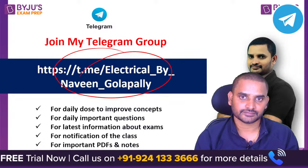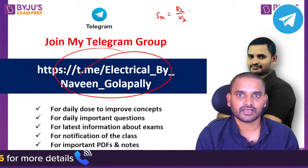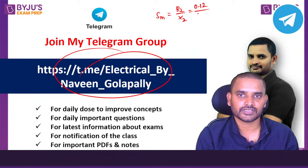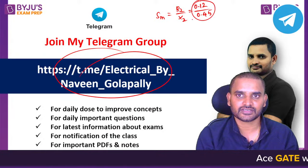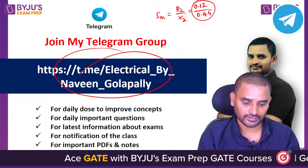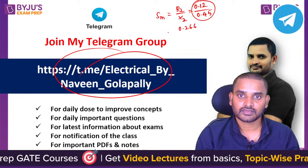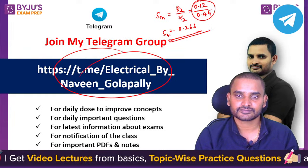Slip at maximum torque, S_m, is equal to R2 divided by X2. R2 we have already known: 0.12 divided by 0.45. This is the slip at maximum torque. You'll get it, solve this. 0.12 divided by 0.45, I'm getting around 0.266. This is the slip at maximum torque.